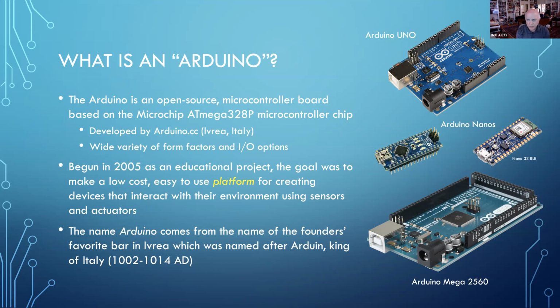So the problem, if you think about it with a microcontroller, is if I give you a microcontroller chip, the Atmega 328P, and I hand it to you, what do you do with it? Well, it's got to have a clock, it's got to have some digital I/O, it's got to have a power supply, it has to have some means of programming. I've got to somehow either talk to it by USB or some other serial interface. So I've got to build all those individual connections up. So what the folks at this consortium wanted to do is take care of all those things, build a single